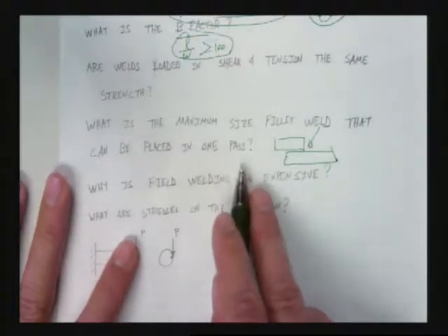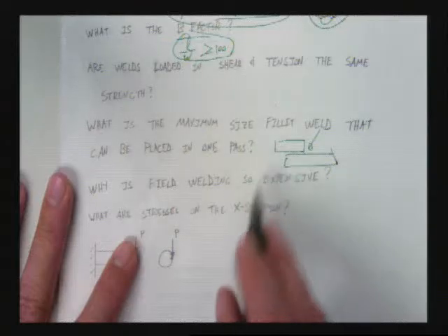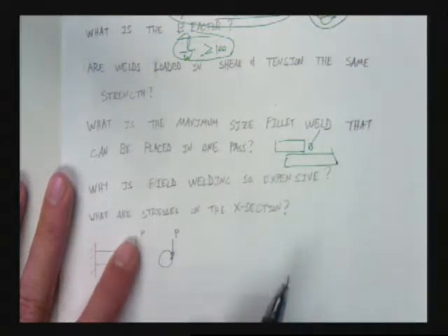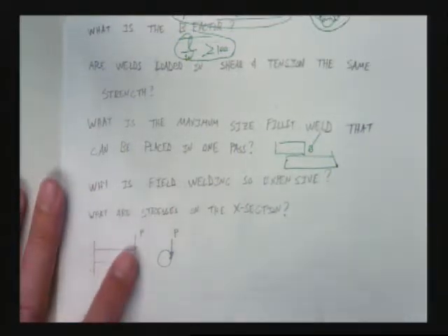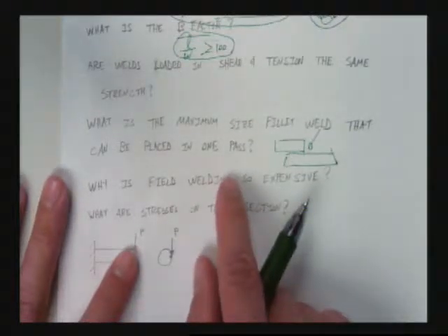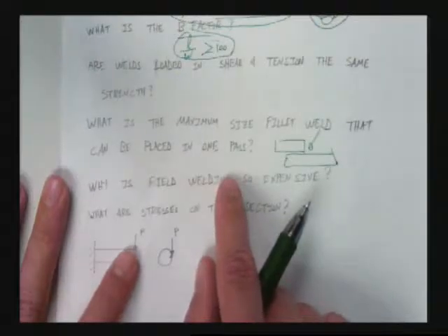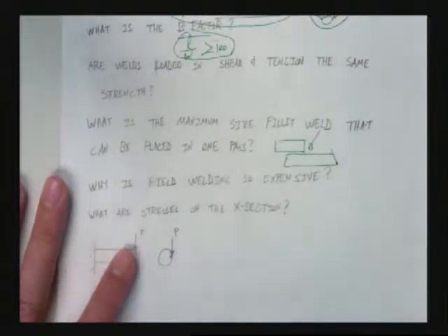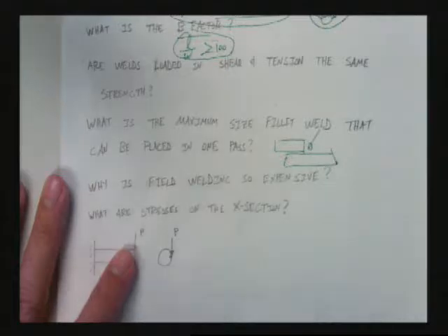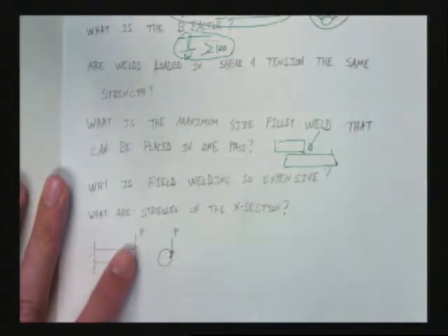And if you can do something to minimize your leg height, to bring it down to 3/8 to 5/16, by changing your length, and it's not going to change other issues, then you should. It's much less expensive and much easier to construct a structure where you can do it in one weld pass as opposed to doing a pass, cleaning it all off, letting it all cool down, coming back, doing another pass on top of it, cleaning it off, letting it all cool down, and then coming back and having to inspect it. Make sense?